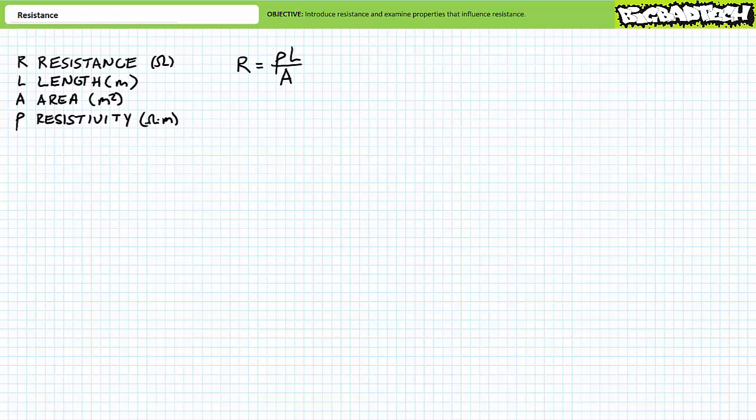Regarding this third property, the innate resistivity of something, what are we supposed to make of this? Resistivity is simply a physical property of a material, similar to a boiling point or a relative permeability of something, meaning it just is what it is. Gold will have innate resistivity different than silver, and silver will have innate resistivity different than compressed cheese. The units of resistivity are all over the map depending on which corner of the internet you're frequenting, but I like using resistivity in terms of ohm meters for reasons we'll learn about later, as in 2 seconds later, as in right now. Do a unit check.